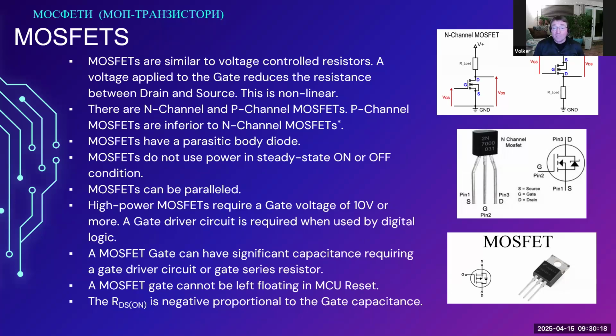is because you will find many circuits where people on purpose attempt to only use N-channel MOSFETs. N-channel MOSFETs have a wider selection, they're easier to get, and they are cheaper for the same parameters. In general, you can have a third generation N-channel MOSFET that is worse than a fourth generation P-channel MOSFET. But in general, circuit designers attempt to only use N-channel MOSFETs.